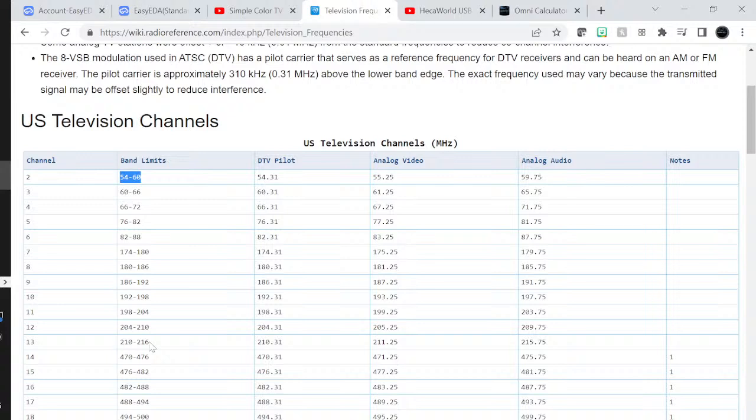So while my antenna could be offering a 50 ohms impedance, for you it could be offering 5 ohms or 500 ohms impedance. In fact, because it's an inverse relationship, it's going to be offering 5 ohms impedance, right? So in that case, it will not match. It will not work as efficiently as mine. And that is why in these videos, I show you why things are done the way they are done, so you don't just copy and repeat.